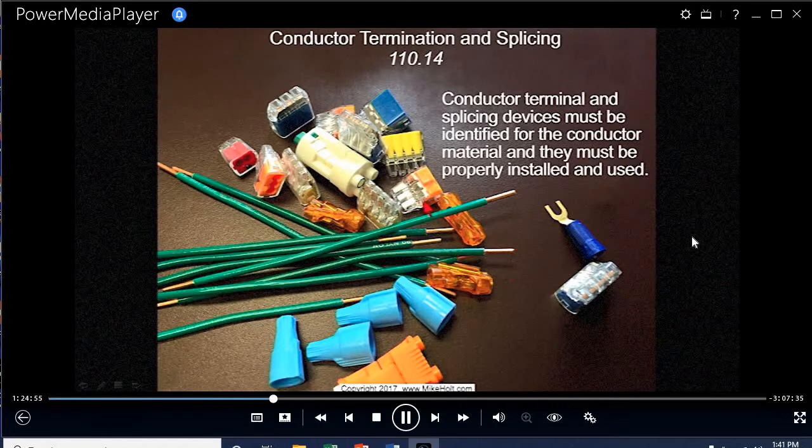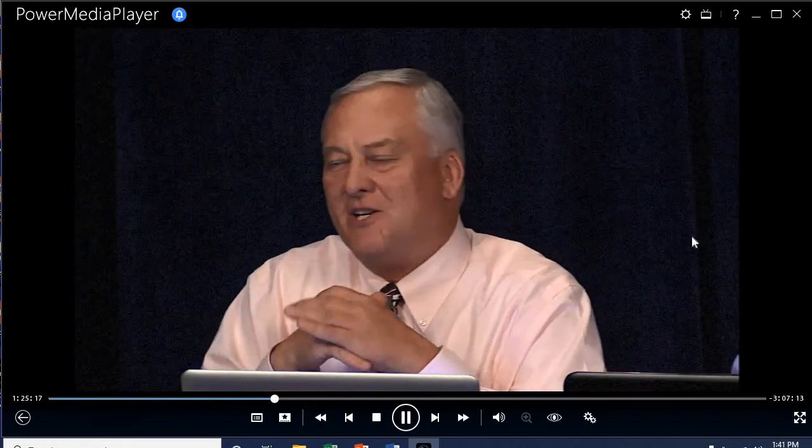So these are what, pressure connectors right here? Oh, here's some pressure connectors. We need to get the twist on, and we need to get these pushed right here. Is that a pressure connector? That's a pressure connector there also. And Mike? Yes. Also, this graphic indicates the push-in type connectors. Be careful on those because they've got different voltage ratings on them. Yep. And so when you go for an inspection, sometimes if you just look at one side, you might think it's a violation because it's got the wrong voltage, but they're dual rated. Okay.